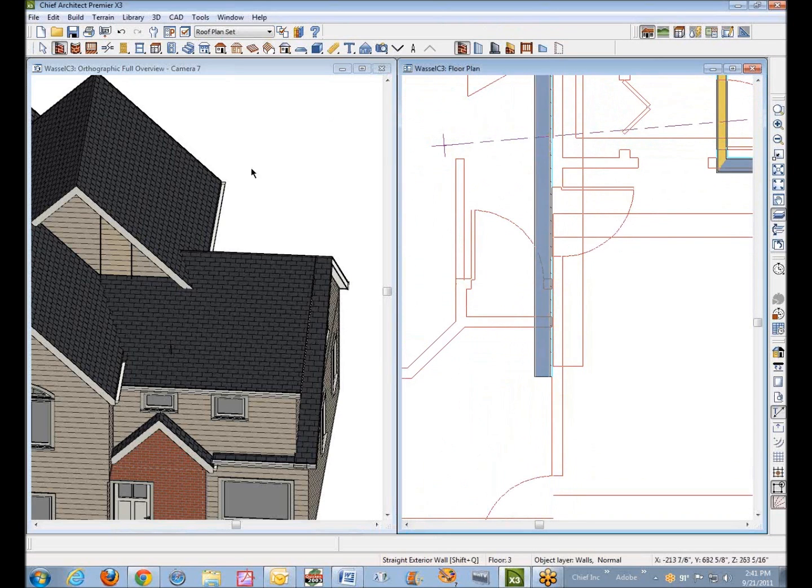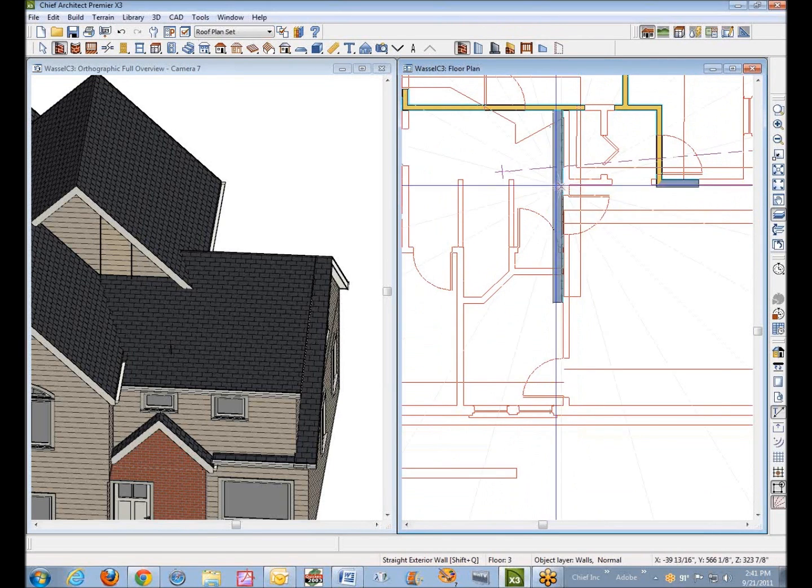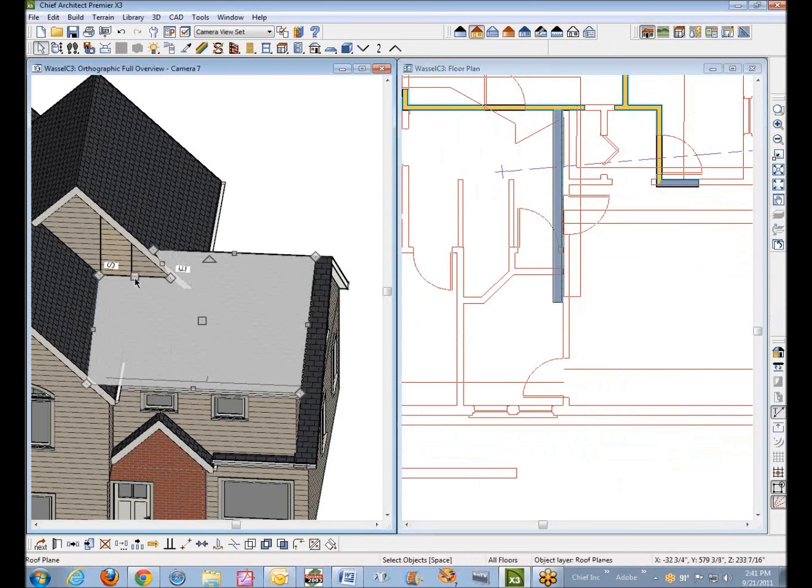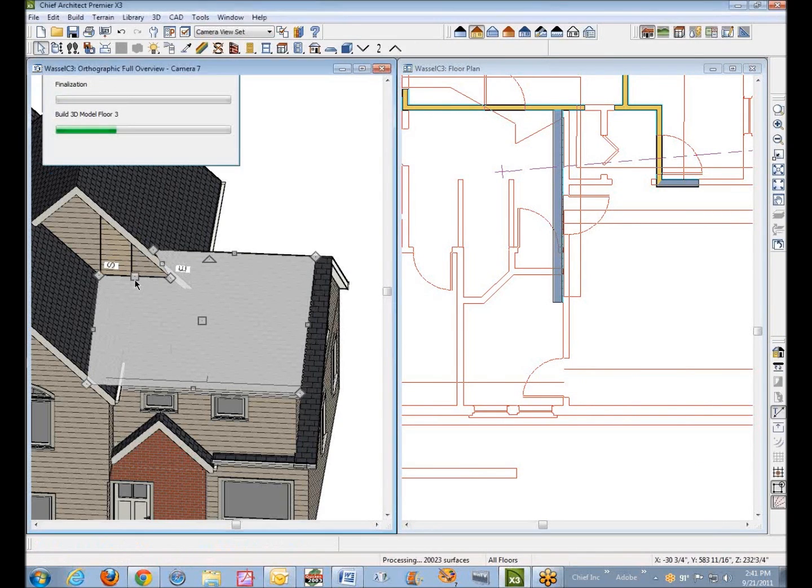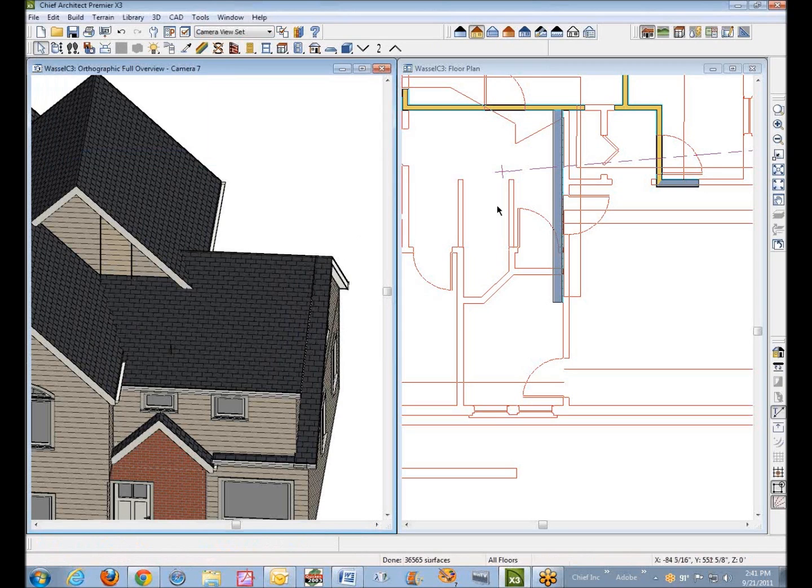It looks like we're getting lines in there, and there, which are kind of unwanted. I wanted to see why. It's still one wall, so I'm not quite sure what's causing the lines, except maybe this edge isn't far enough down. I'm going to pull it down. I pressed the control key, by the way, so it doesn't move more than I just want to. I'm going to hit F12 to rebuild walls, floors, and ceilings.